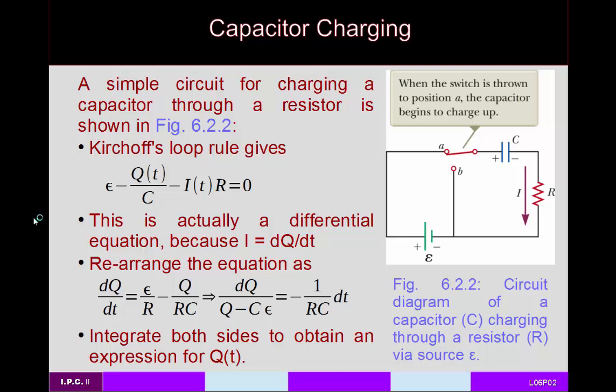We'll start with how a capacitor is charged and how to model the charging of a capacitor. What you see here to the right is a simple circuit for charging a capacitor. By the way, this right here is a switch, so if we switch it, the part that's in contact with A will switch to being in contact with B, and so the loop no longer has a battery in it. The loop will just be this part. Right now the loop is around like this, and you don't really get current flowing to B.